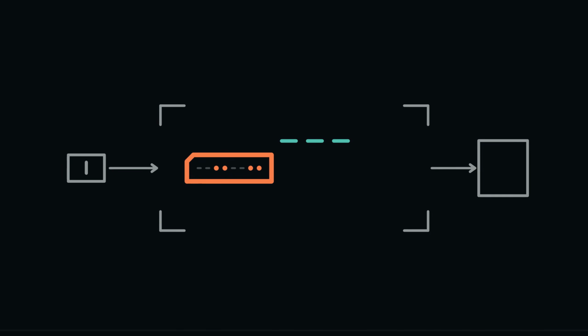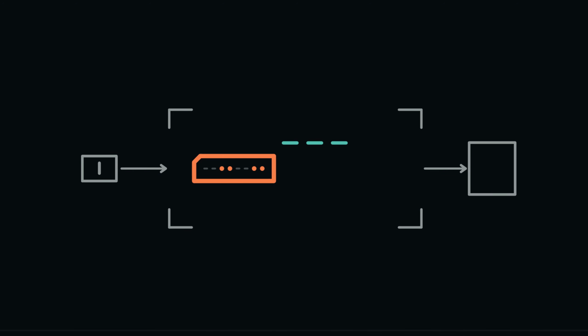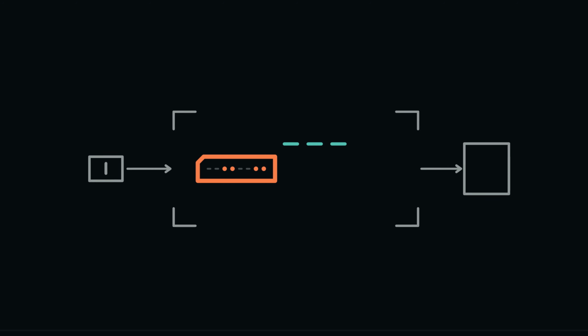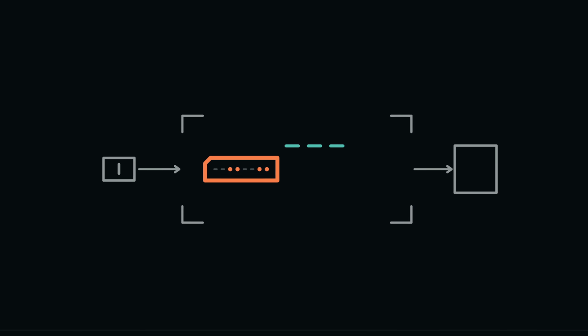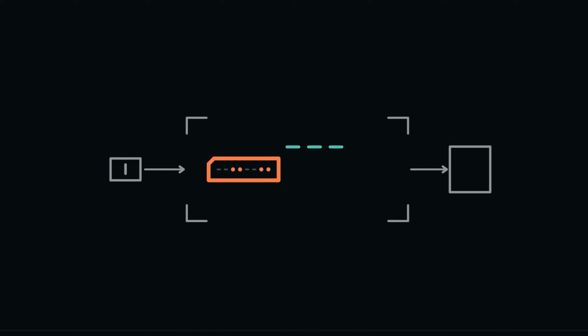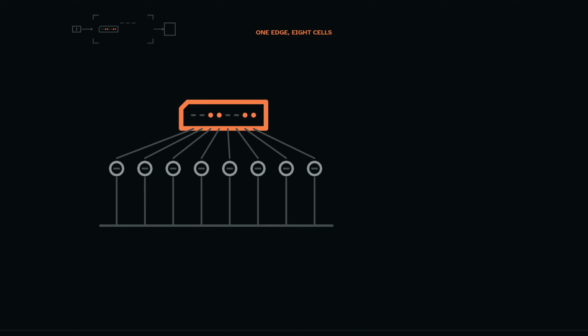One edge-triggered cell can preserve 1 bit. Our notched carrier contains 8 ordered bits, so place 8 proved cells beneath its 8 positions without changing their order. Every cell receives its own data bit. All 8 share the same active clock edge. Before that edge, the incoming pattern is only a proposed next value. At the edge, the 8 cells capture their corresponding positions. After propagation delay, the stored outputs present the complete pattern together. This aligned group is an 8-bit register.